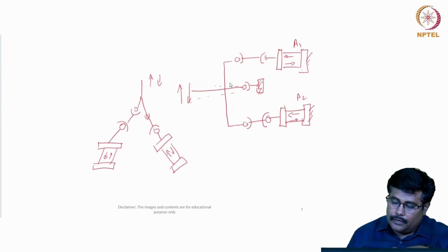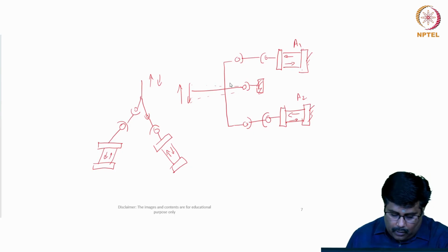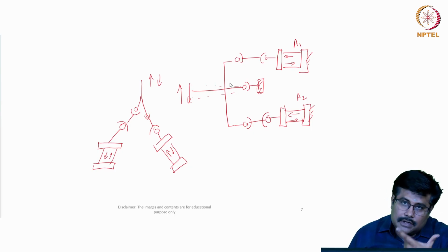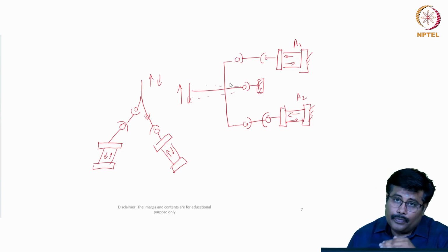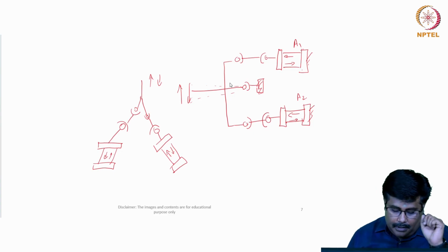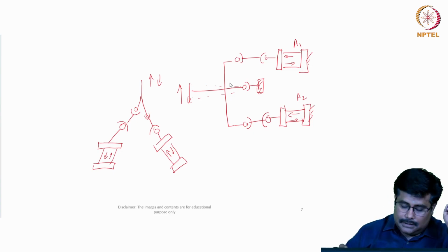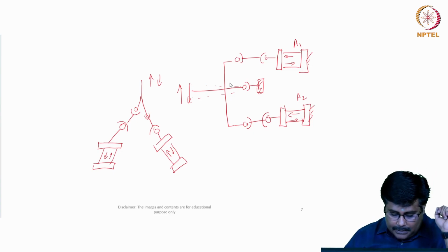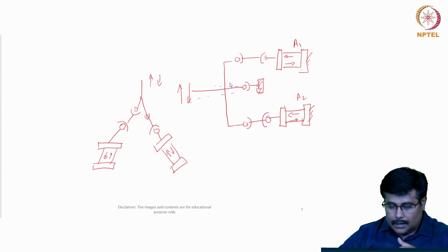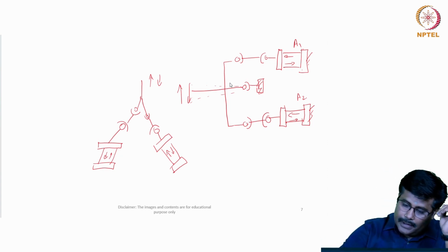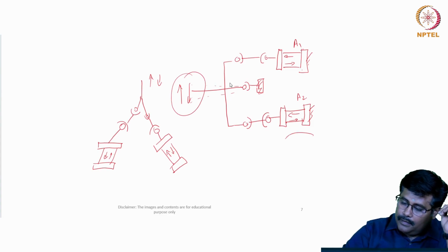So in this configuration, we have two actuators which are mounted, so that when one shrinks, the other one elongates. The amplification gain is provided by the lever with a pivot. So the push-pull configurations can be adapted to any configuration, so that these two actuators can move the same amount in the same direction. So based on the requirement, appropriately we can manipulate the movement in both directions.